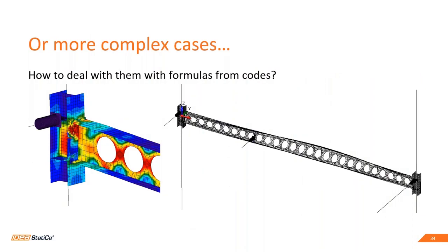And of course, you can use this application on more complicated cases. For example, this is a castellated beam with circular openings. There are some cleat connections, and you can see that the bracing, which is located in approximately 1/3 of the span, has a big influence on the eigenshape.